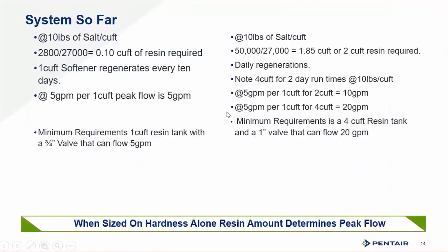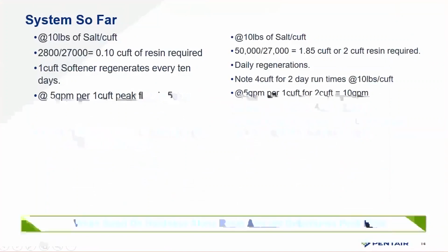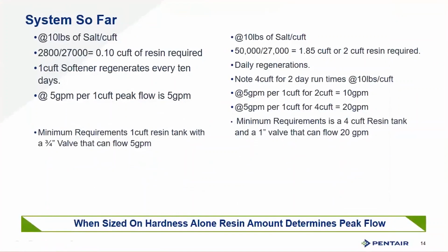Okay, it's critical to understand here that what a valve can flow is not what the resin can flow. That's one of the biggest mistakes in treatment, not understanding that difference. Whatever we put in the tank determines the flow rate we can put through it.